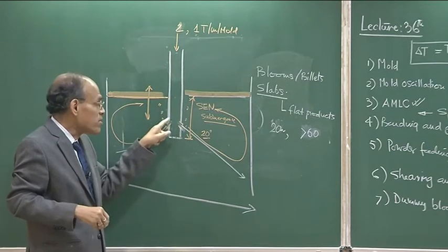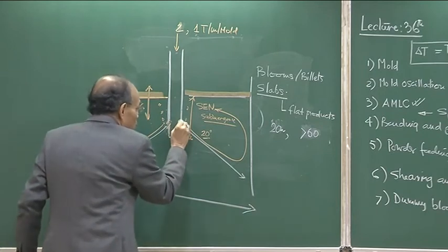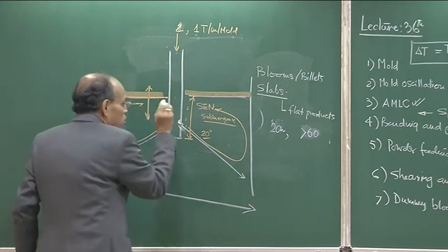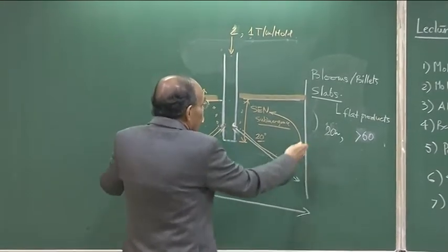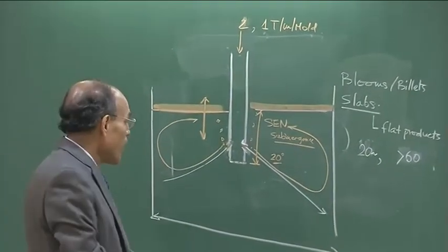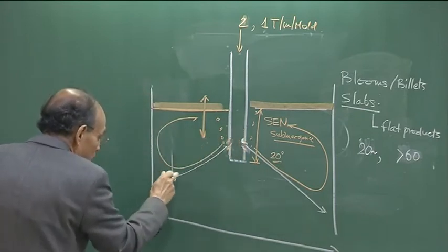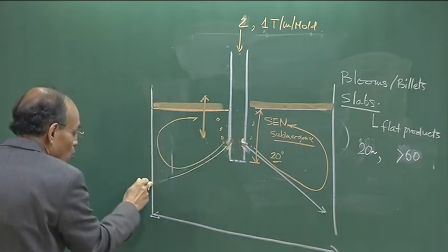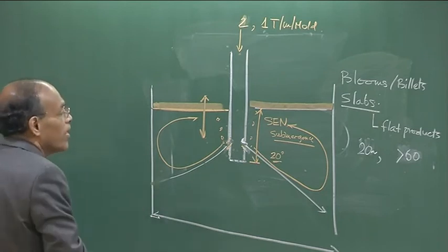They may develop defects, there may be deposition, and the flow may happen to be biased. Suppose you have deposition taking place on this nozzle because of some irregularities; flow will try to predominantly go through this, and as a result this characteristic twin roll pattern is going to be disturbed. Then more liquid comes out through this, and therefore it strikes the wall with more force. Or the solidification front end remelting, etc., can take place.